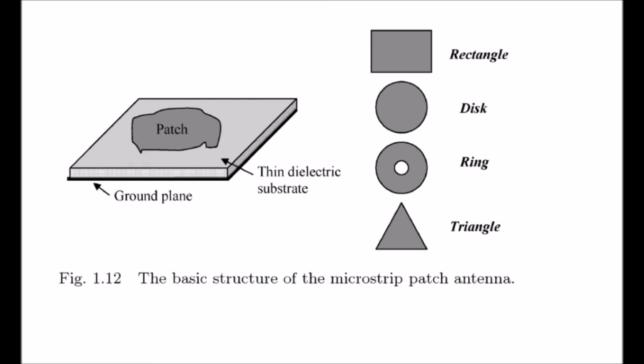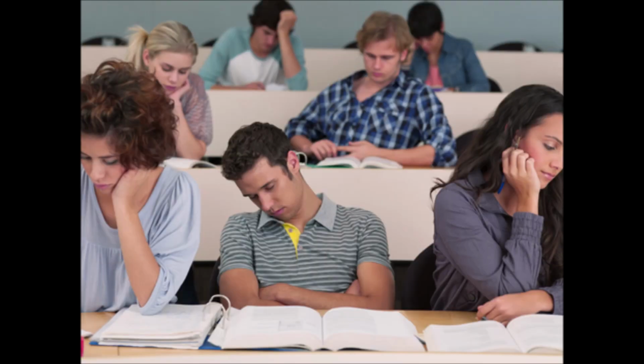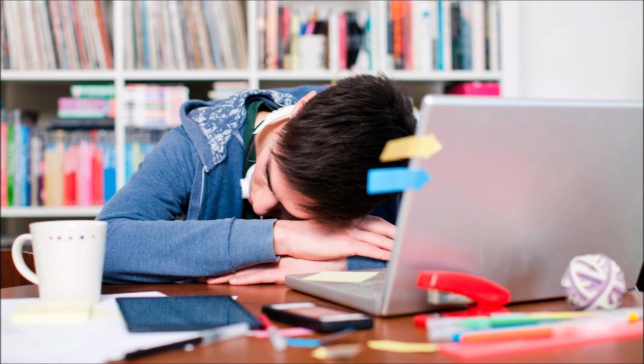Number 3, those with a relative dielectric constant between 4.0 and 10.0. This type of material can be ceramic, quartz, or alumina. The most commonly used material is Teflon-based with relative permittivity between 2 and 3. This material is also called PTFE, polytetrafluoroethylene.